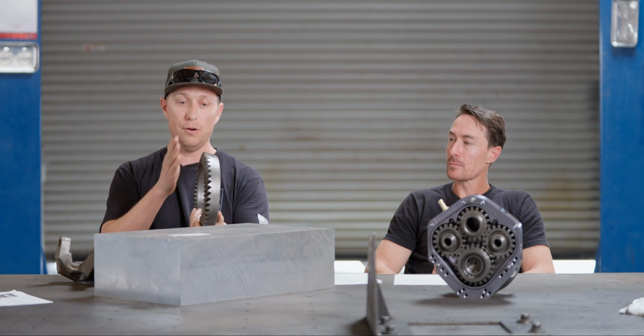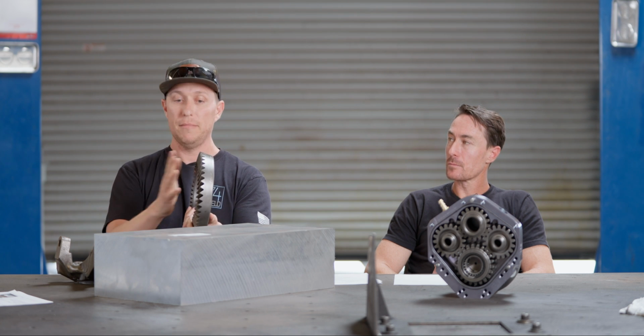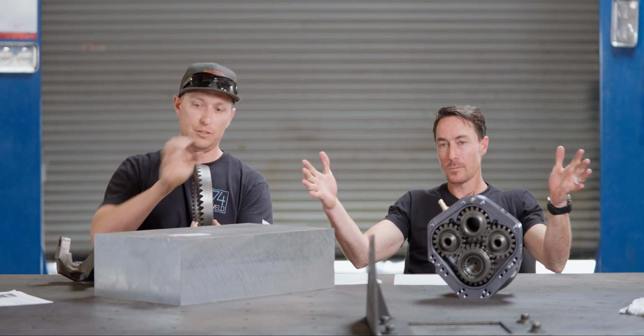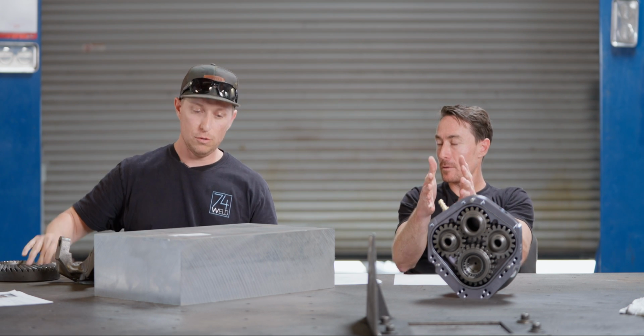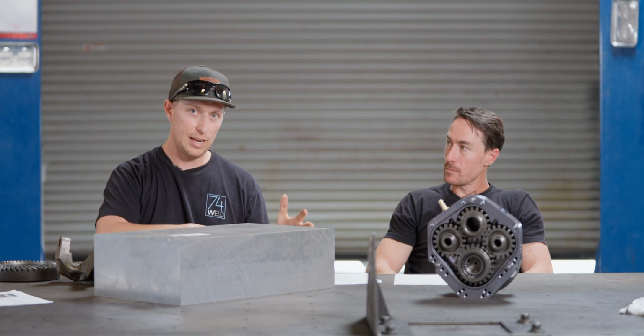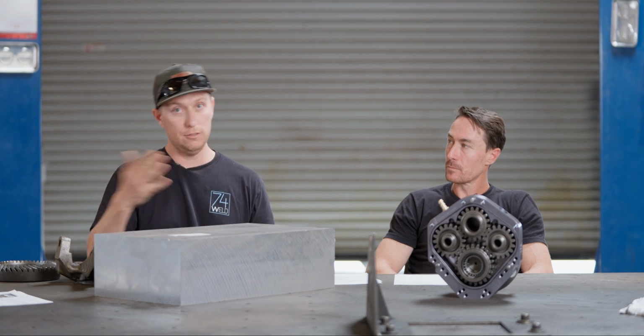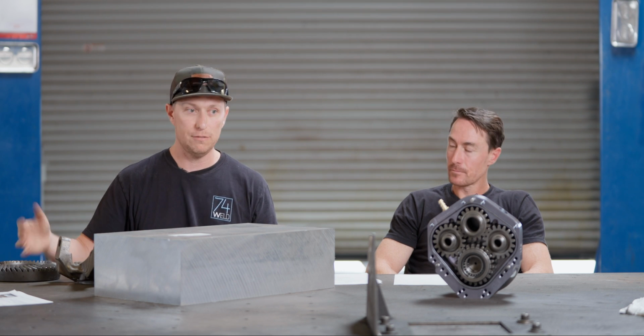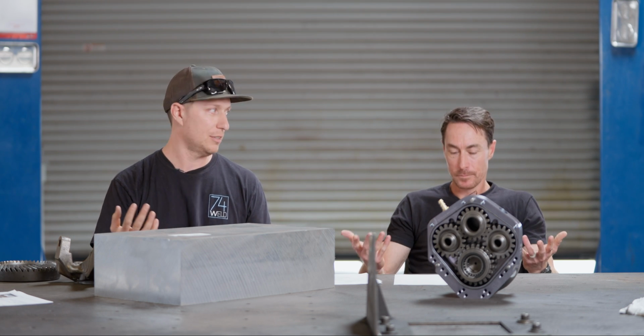Draw a line down the middle. Say that's a board. Half of the positive will be on one side of the board, half of the positive will be on the other side of the board. And then you smash this match plate into sand to create a cavity. And then you do that on two boxes, you put them together. Now you have a cavity that matches the positive. You pour metal in, it cools, and now you have your part.